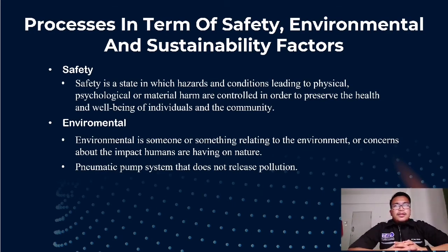Besides that, the cloth on the filter is effective because most substances are attached on the cloth while the water passes through. The type of filter cloth used on the filter is polypropylene. As we know, polypropylene is the most common material. It has strong resistance to acid and alkali. A satin finish added to the fiber can allow for easy cake release.